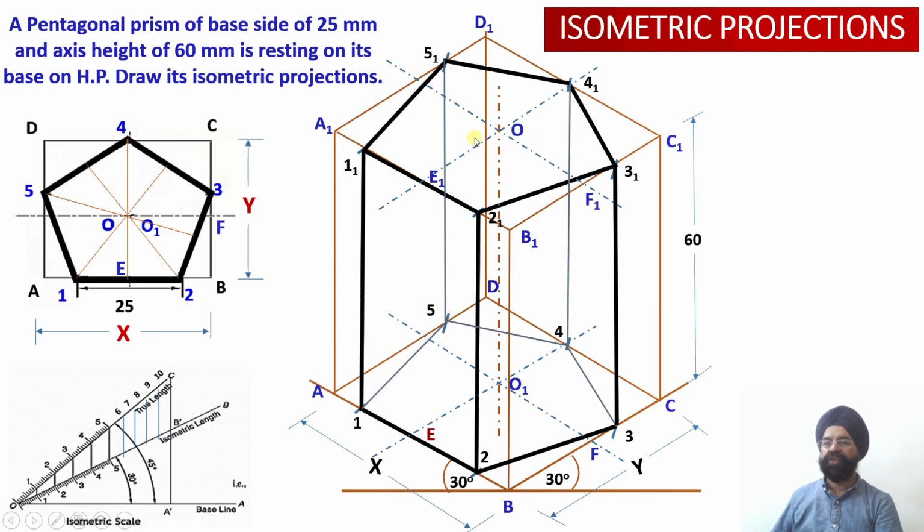So the top face, all the edges are visible. In the bottom face, couple of edges they are visible, but the remaining 3 edges they are not visible. So 2 of the vertical longer edges they are also not visible, whereas you are able to see the remainder 3 edges of this pentagonal prism, which is lying in its vertical orientation. Earlier one was the horizontal orientation, right?